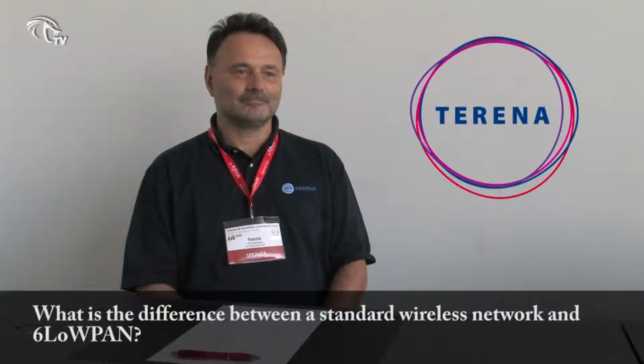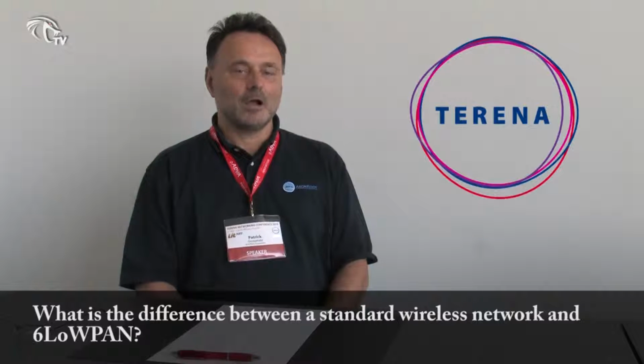What is the difference between standard wireless network and 6LoWPAN? The fact is, if you look at the past, the wireless networks were not using IP as the technology. So they were using closed systems. And for example, if I try to compare with Zigbee, which is also well known, Zigbee has been recreating the whole stack for the communication. But if you look at today, everybody is using the internet, and everybody is using a web browser to get the information. So our idea was, why don't we just use the same hardware chipset from Zigbee, but put IP on top of that? So now the sensor node is just part of your IP network.